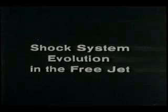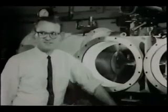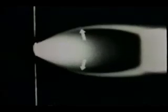Now we'll look at a continuum flow from the same nozzle, but without the model. This flow has its own well-defined system of shock waves. The barrel shock and the Mach disk. We see a somewhat similar pattern of shock waves in the exhaust of rockets. These shock patterns are only clearly defined when the mean free path in the background gas is small compared to a characteristic length like the distance from the nozzle to the Mach disk. Under these conditions, the shock configuration depends only on the pressure ratio across the nozzle.